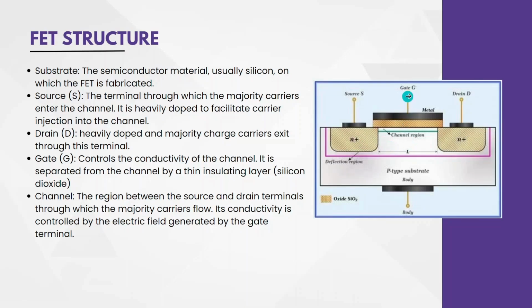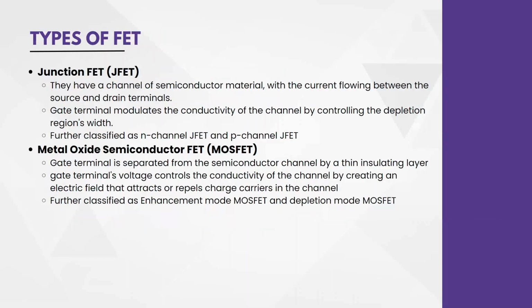To this, we have the gate terminal connected, which means by controlling the voltage at the gate terminal, we can control the behavior or the conductivity of the FET. Under this, we have JFET and MOSFET as discussed. There is not much difference in the function, but it just depends on how it is designed.